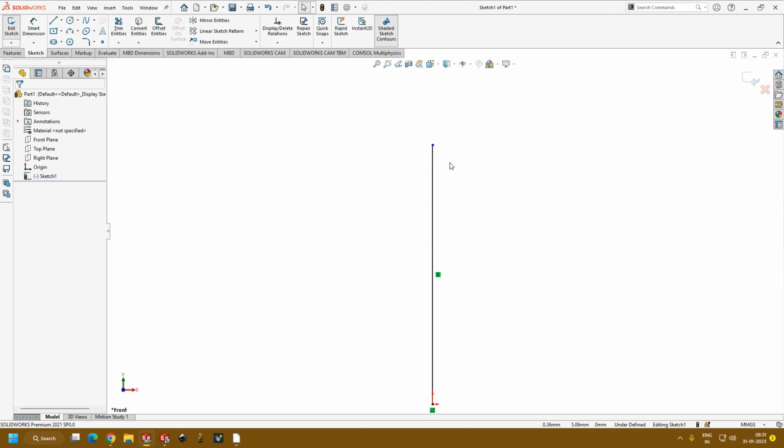During iterations, you may require only one dimension to change all the time. But if the sketch is undefined, when you change one dimension, all the dimensions will get affected. That is the reason every time your sketch has to be in fully constrained mode. To do that, you just observe which blue point is left in the design. Since it's a simple line, it has only 2 points, start point and end point.